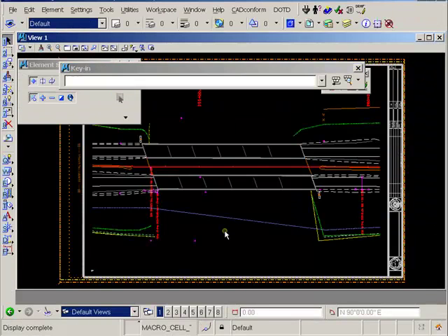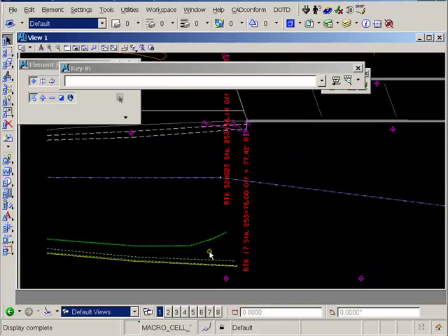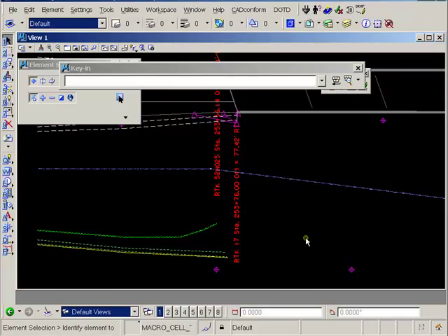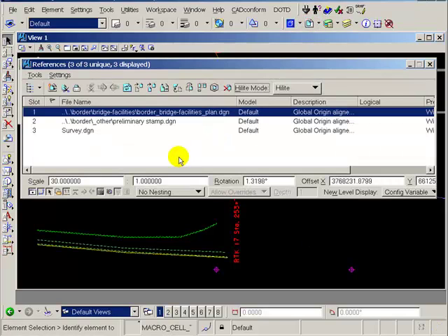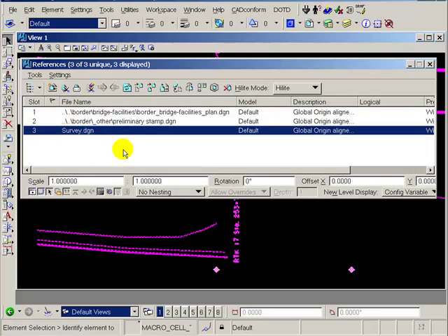Now I will open the site plan file. Remember, I have already set the global line style scale in this file to 30. Because I changed a hard-coded line style scale to 1 in the survey file, I need to toggle on a setting in the reference file dialog.